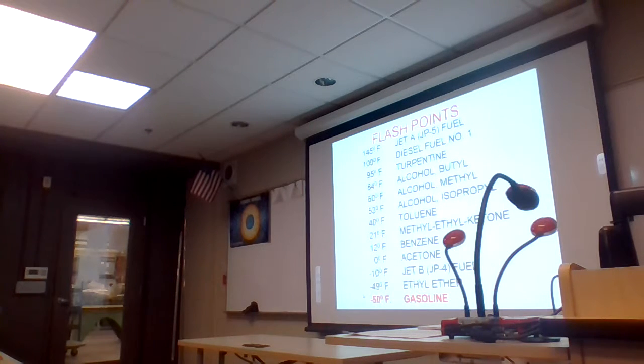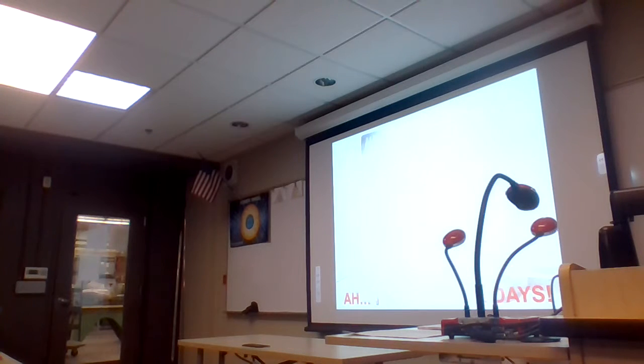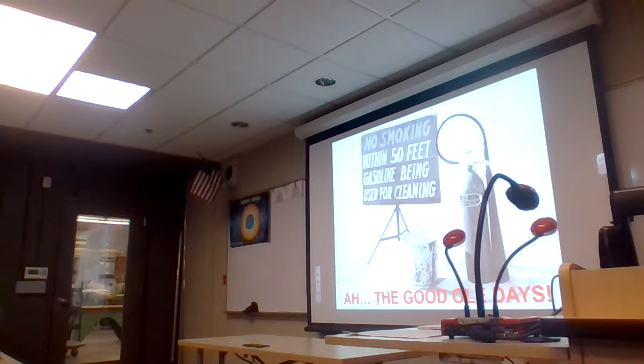I realize in the past, during World War II, they did a lot of wacky stuff. You look at some of the old service manuals and they'll say, oh man, we're going to use gasoline for cleaning. That was an expedient method during World War II in Africa, okay, but not here in San Diego, okay? So again, that's not an acceptable cleaning material. No way.